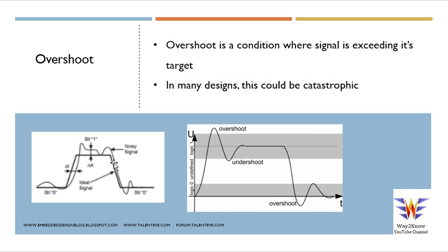So overshoot definitely is a very dangerous criteria, because the digital systems are restricted to operate at certain levels. So if we apply a voltage level beyond certain characteristics or its specifications, even the vendor who has submitted that IC may not be able to predict what could happen.